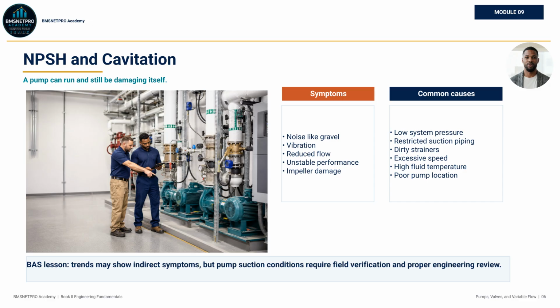Common causes include low system pressure, dirty strainers, restricted suction piping, high fluid temperature, excessive speed, or poor pump location relative to the expansion tank connection. When you hear a noisy pump, do not simply lower alarms or force the pump harder. Investigate the suction conditions.